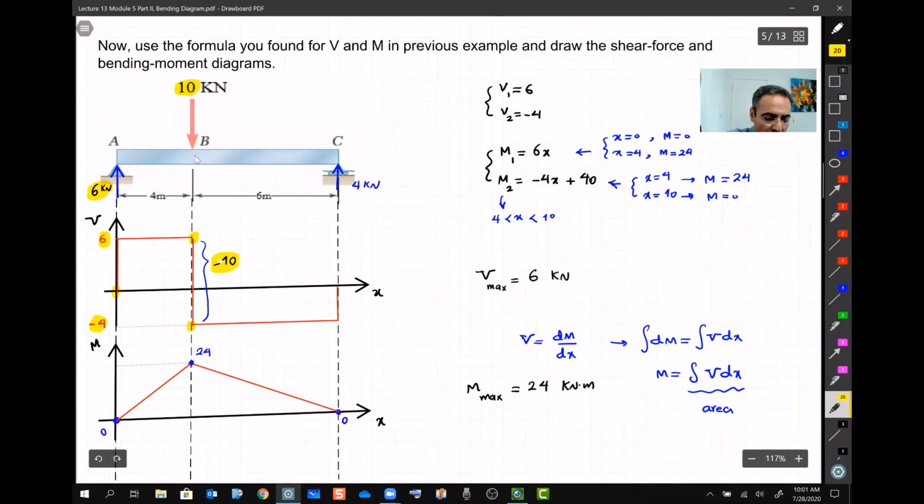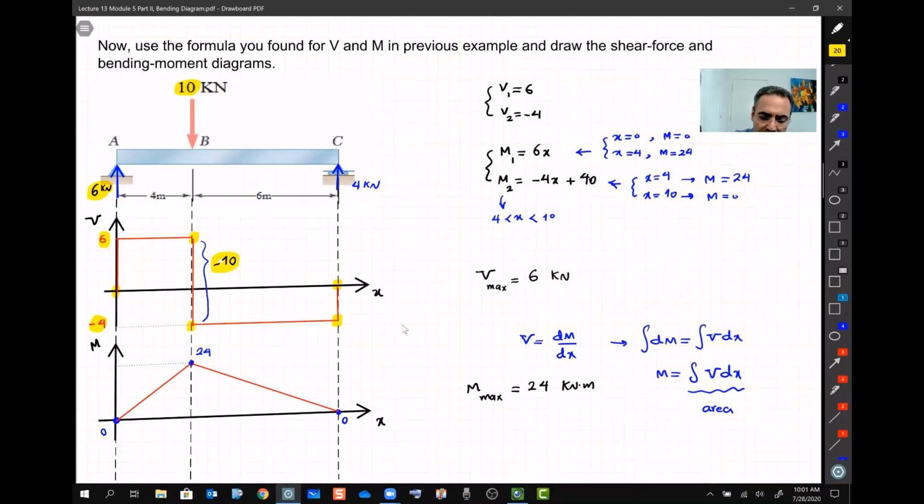There is nothing going on the beam, and it's just a constant line going all the way down until here. And then here on the beam, we have 4 kilonewton upward, right? You see there is a jump of 4 going all the way back there. So remember, we start from 0, we return back to 0 because it's equilibrium and everything has to go back to 0.